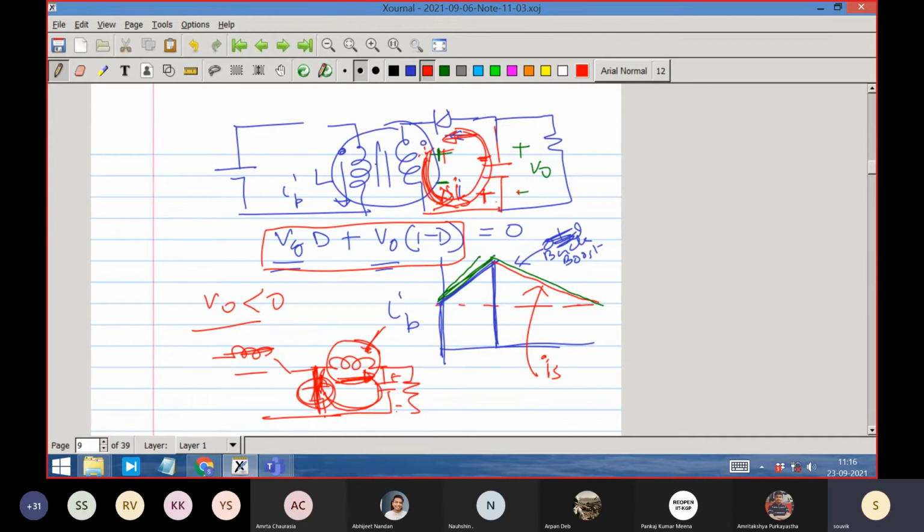It sees that the diode is consistently placed, because its anode is in the same direction as the current needs to flow. Earlier the current flowed from dot to cross. This current also has to flow from dot to cross to maintain the flux, right? So it will take that path.